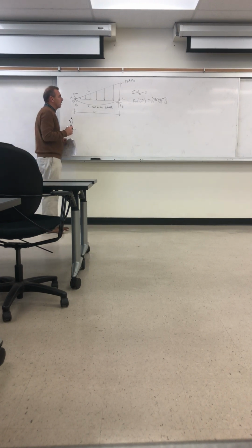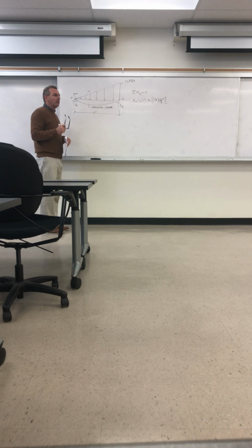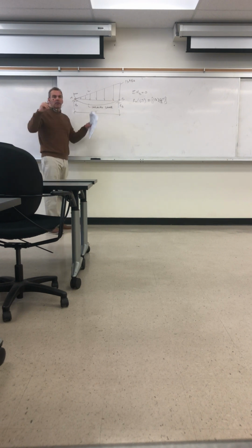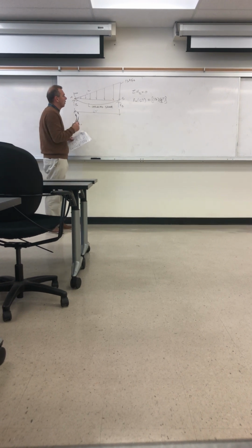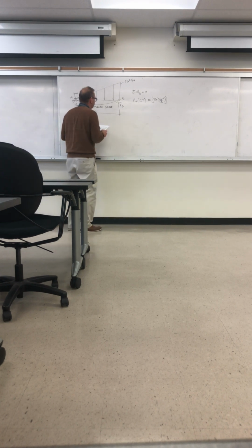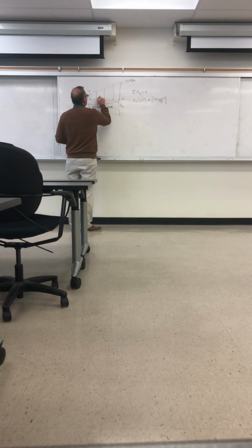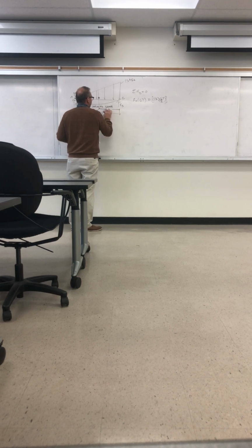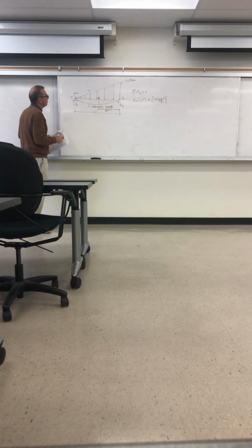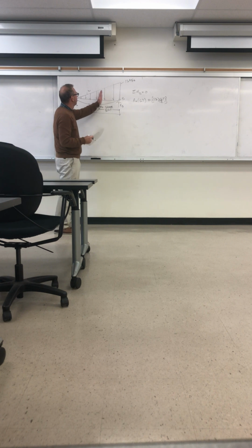And then that's going to equal the counterclockwise moment from the varying distributed load. So it's 13 times 67 over 2. That's the total force applied down. And then we just multiply that by the moment arm, which is 1/3 of the length, right? So this is the centroid. That's 1/3 of 67. Centroid of the triangle. It's over here.